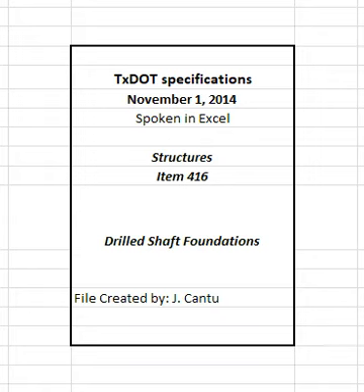Maintain a sufficient head of concrete for cased shafts at all times above the bottom of the casing to overcome hydrostatic pressure. Extract casing at a slow, uniform rate with the pull in line with the axis of the shaft. Monitor the concrete level in the casing during extraction. Stop the extraction and add concrete to the casing as required to ensure a completely full hole upon casing removal.